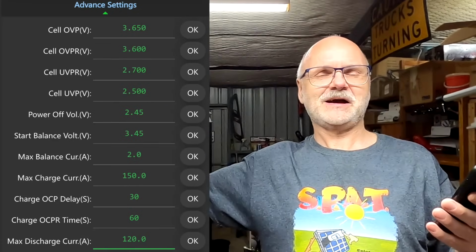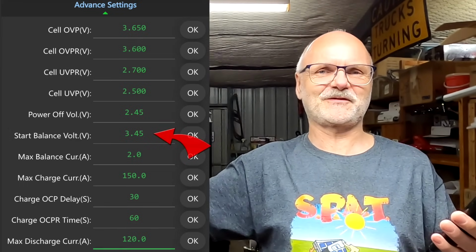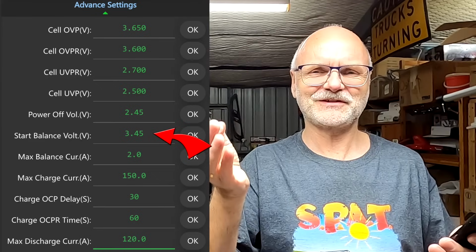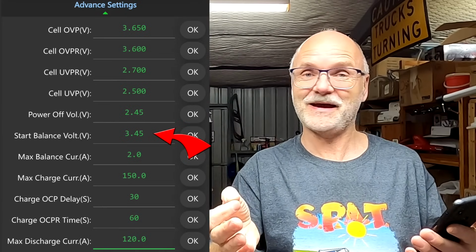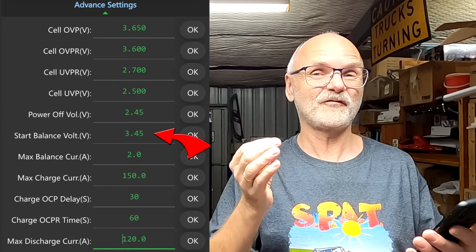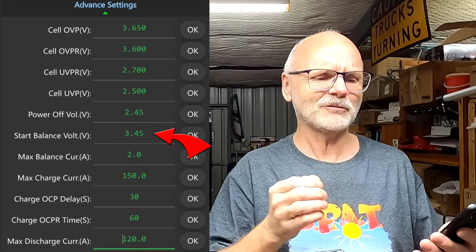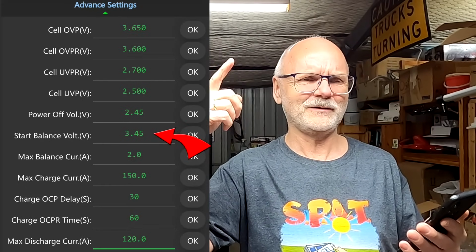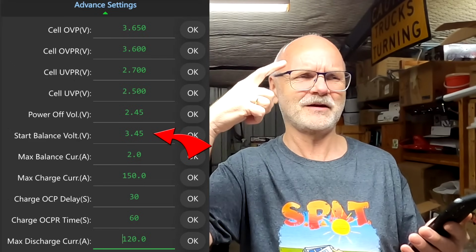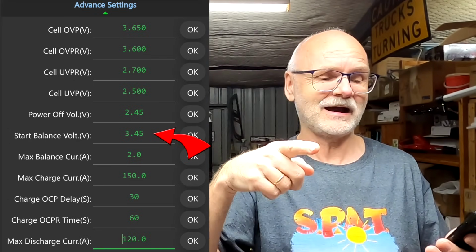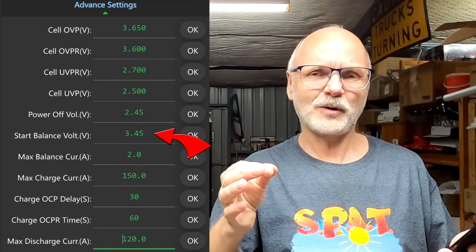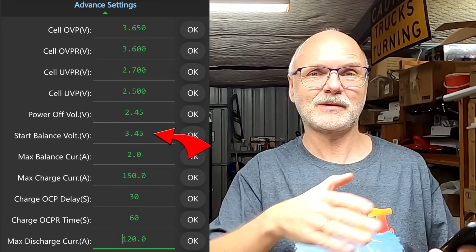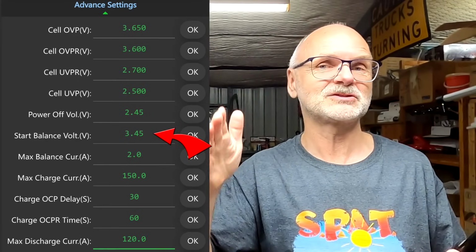And then finally, we come to the start balance voltage. This is one of the most discussed values in the BMS, and I've set mine to 3.45 volts. You may remember this number from many of my videos I've done in the last 1.5 years here on the channel. 3.45 volts is my magic number because this is the maximum I charge my cells to.